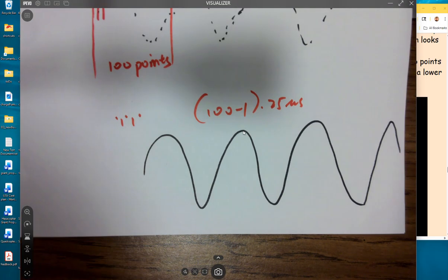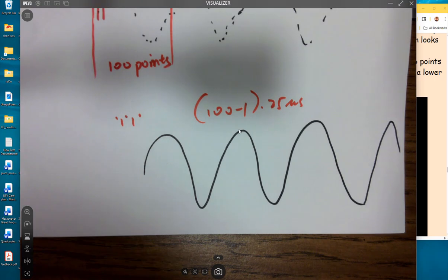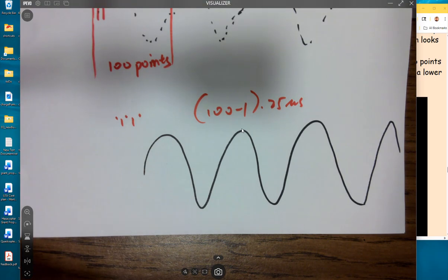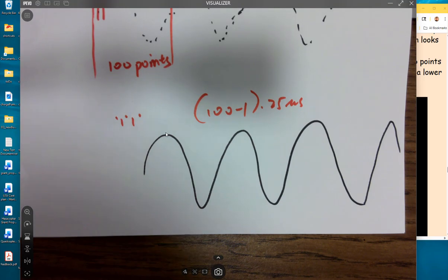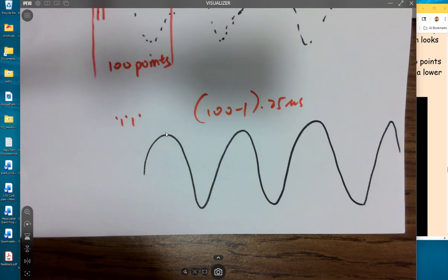So what if we are checking the peaks, right? If you reach 2 peaks, you know that between the 2 peaks it's going to be 1 period. So between 2 peaks will be 1 period, right? But how do you check a peak? Just based on the values being sampled and put in the buffer. Max, but how? It won't be Python, right? A CPU or laptop can do it, but you are actually accessing the register level of programming and taking out the bytes. It's basically just bytes.